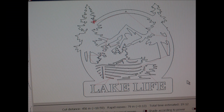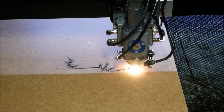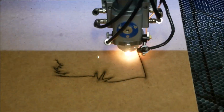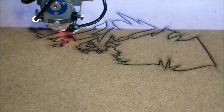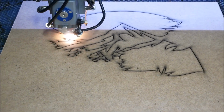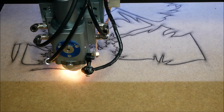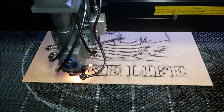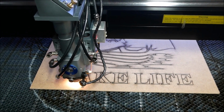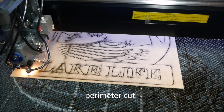I've loaded the DXF file into the CO2 laser software. I'm using a 300 watt laser, and the bed's 39 inches by 52, so it's a large bed for large projects. In the settings, I'm using a low power and low speed. Pretty well finished up here. I'm just going to cut out the perimeter, and that'll be it.